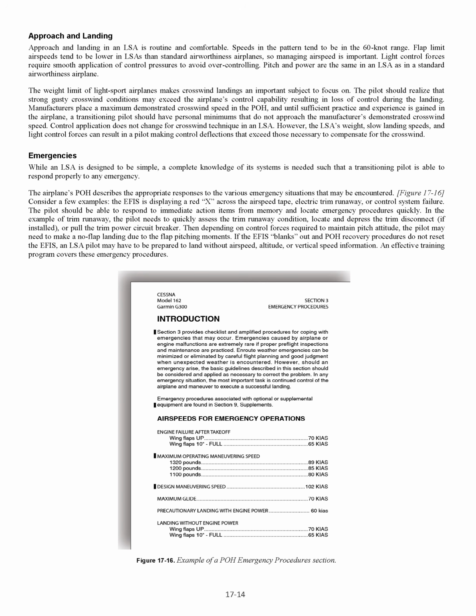Control application does not change for crosswind technique in an LSA. However, the LSA's weight, slow landing speeds, and light control forces can result in a pilot making control deflections that exceed those necessary to compensate for the crosswind.